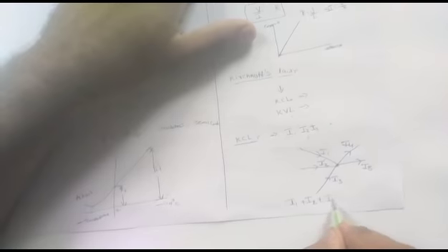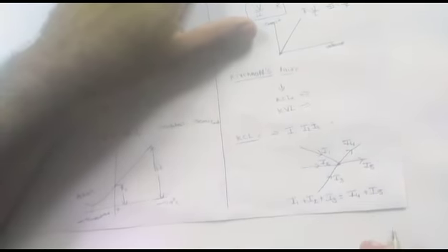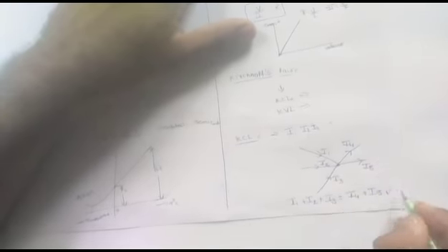So these three currents are entering a point, and only two currents are leaving. Let us consider these two currents as I4 and I5. From the KCL statement we can simply denote I1 plus I2 plus I3 is equal to I4 plus I5. So this statement will be satisfied according to the KCL statement.